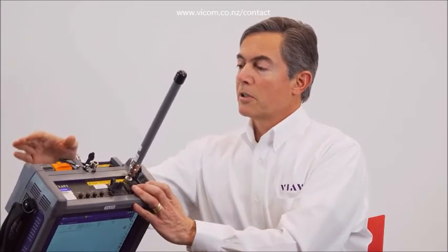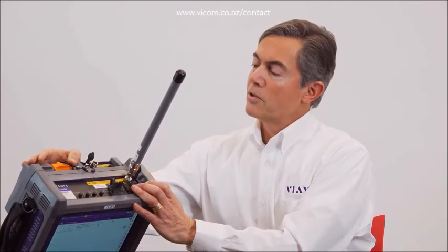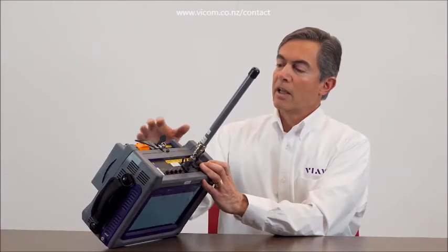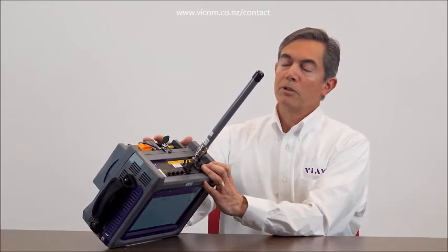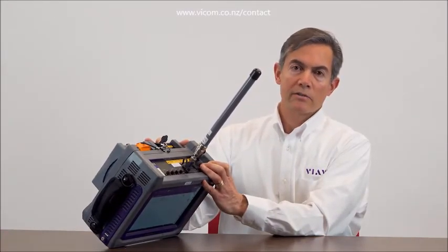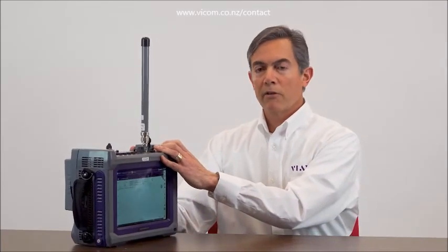In 5G deployments, there are different topologies. One of the topologies that is mostly being adopted nowadays is with DWDM. And to have a full characterization in DWDM signals, in addition to conducting OTDR tests, with dense wavelength division multiplexing, we need to characterize each of the channels. And that's going to be conducted with a similar module that is the channel checker. That's going to give us full visibility of all different wavelengths transmitted on that fiber.